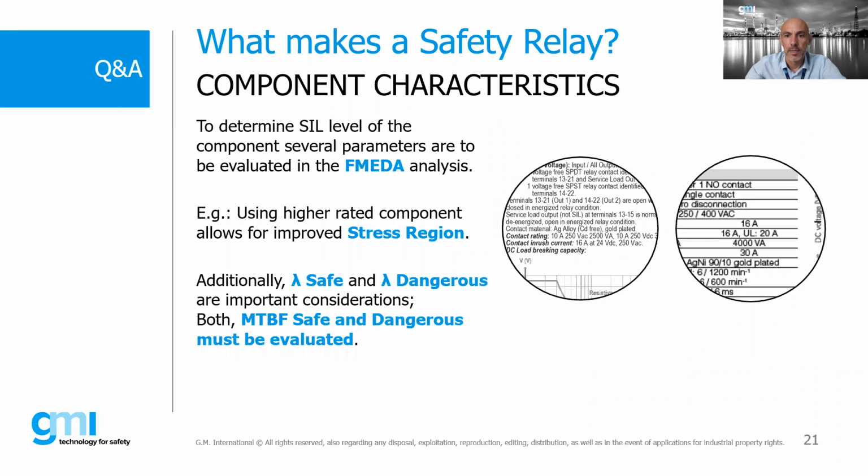And the last, of course, is the FMEDA analysis. The FMEDA analysis gives you details like PFD, probability of failure on demand, and the MTBF, mean time between failures. The FMEDA analysis for relays is the result of the analysis of all the components inside.